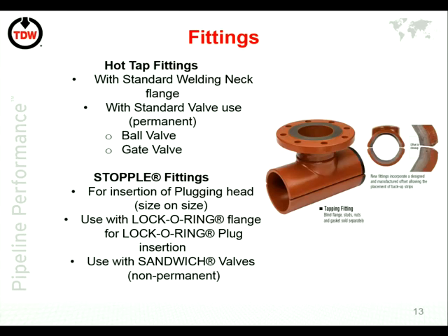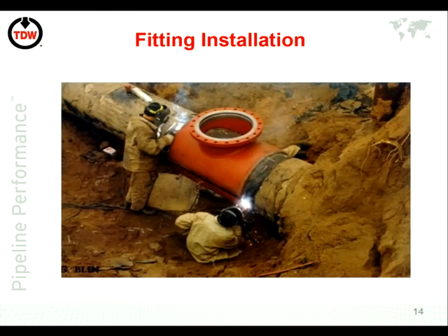As mentioned earlier, the criticality of the fitting going on right is so important to the installation process. So this is just a typical site setup, and you can see the welding occurs around the outside, so that will be either side, and then it will be across the middle as well. This is obviously the area that we're going to be tapping. So the orientation of it is obviously key. If it's a 12, this is a 12 o'clock fitting, so it has to be exactly at 12 o'clock, because if it's slightly off, that means the branch that comes off will follow that route.